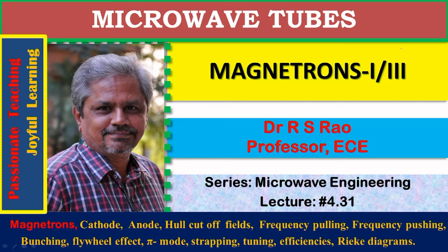The cathode is surrounded by a thick block of cylindrical tubular anode. In the structure of the anode, there exist several cavities. These cavities act as resonators. Usually, the cavities are all identical, and in most cases, they take the shape of a hole slot combination. In between cathode and anode, there exists a certain cylindrical space. It is called the interaction region.